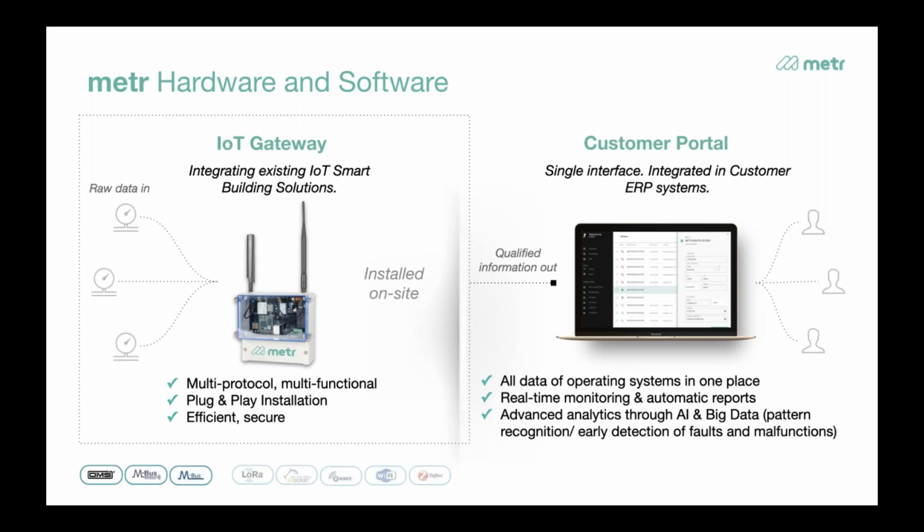In general, we start with grabbing the data from existing hardware like heat or water meters or temperature sensors or current sensors we retrofit in the field, because we do not usually have those data points available. And then we feed this raw data from the different devices and different manufacturers via our gateway and via LTE into our platform.